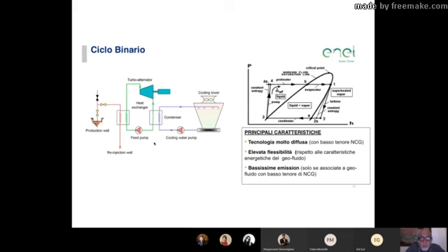Although they reduce the pressure of the geothermal system significantly, and you have a lot of emissions to the atmosphere. So only if you have very good geothermal water, mainly water, can you safely use these power plants. Otherwise, you produce a lot of emissions, both gaseous emissions and solid or fine particle emissions.